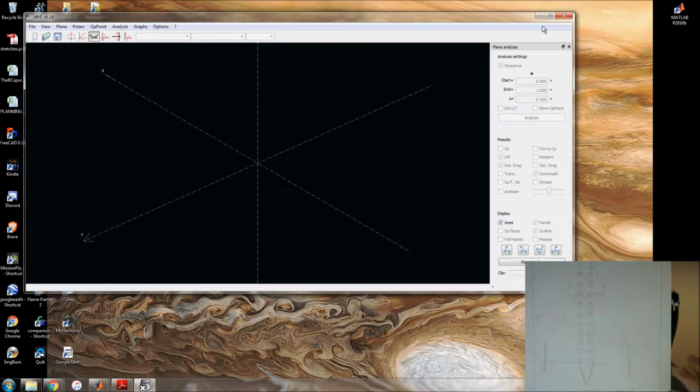You can pick anything, just make sure that you've identified a scale. So doing that as 1.2 meters ended up being that my scale, if you can see it, is 50 millimeters to a side on this graph paper. This is engineering paper, so it's kind of faint, but it is graph paper.